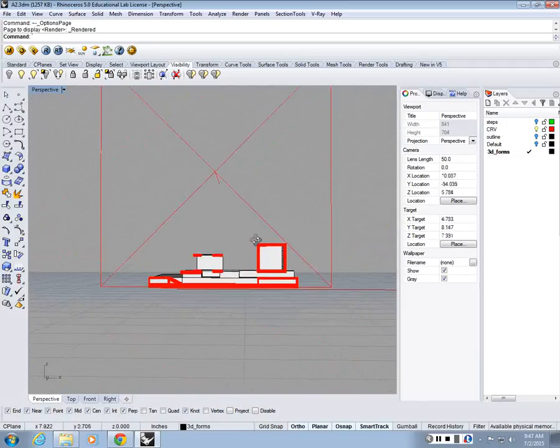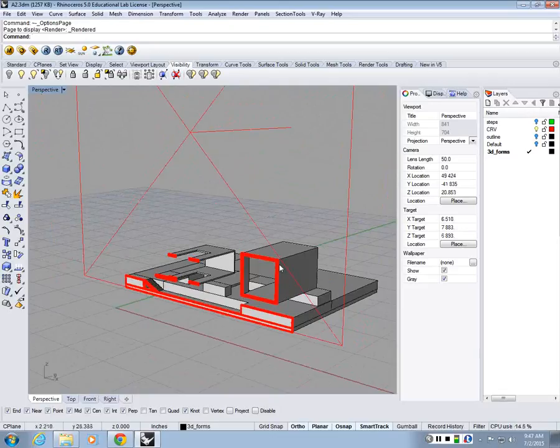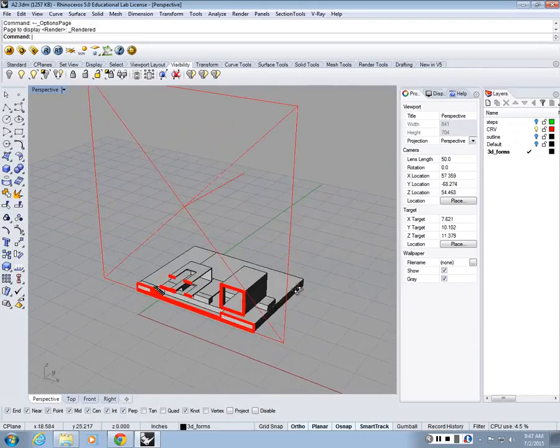Okay? So I'm going to do 2 things. I'm going to generate a section drawing. I'm going to create a layer here and generate the section lines, and then I'm going to make 2D of what the view is and use that as a 2D template to override in Illustrator. Okay?